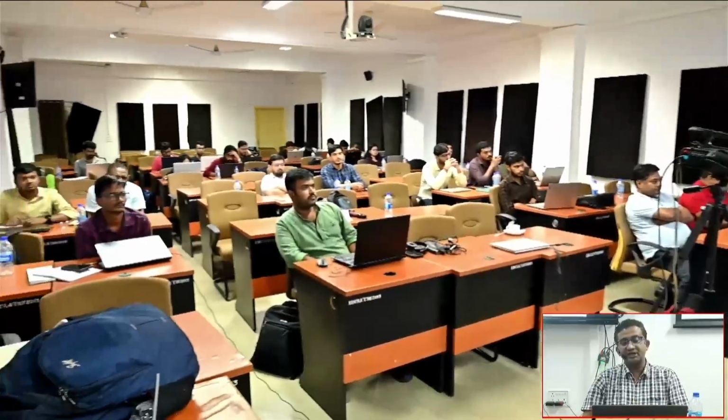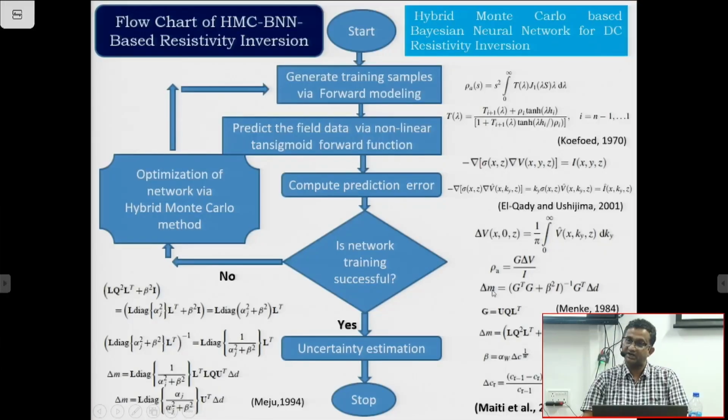Okay, so the del M actually contains the information of the true resistivity of the layer and the thickness. Now the question is how many layers are there. That is up to the interpreter. They have to play with that. Say it is a 3-layer case or 4-layer case, and accordingly provide the initial guess about the resistivity value. Then only it will be able to calculate the apparent resistivity, and then fitting will start, observed versus prediction.